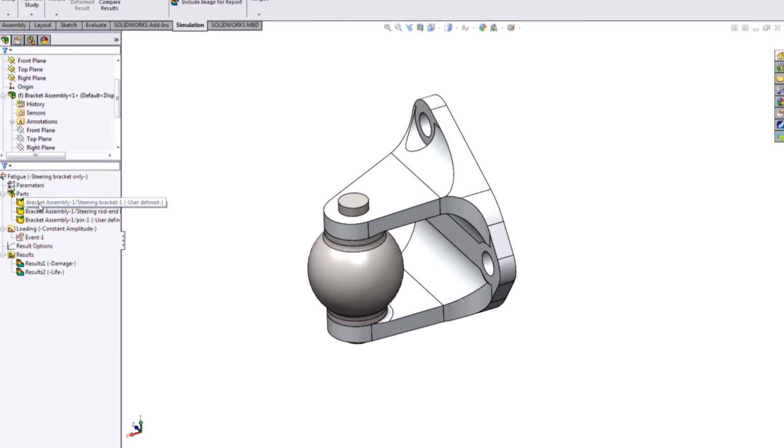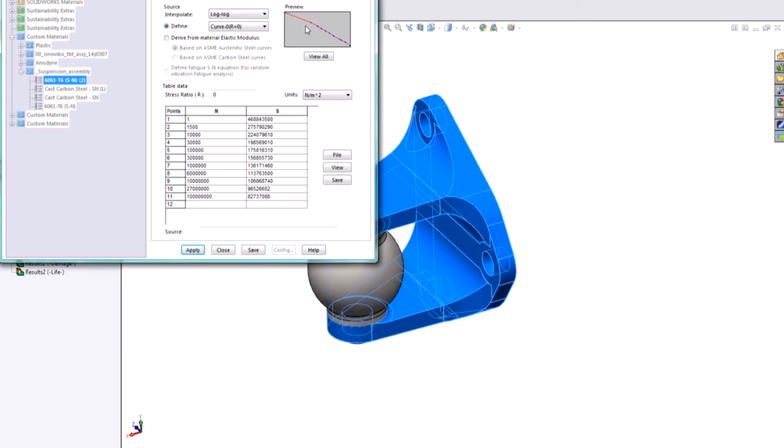And we can run a fatigue analysis here. This fatigue analysis is based on an SN curve for the materials. You can either read them in, or you can use an approximation. There's a couple built into the software. This SN curve defines how that object will react to fatigue.